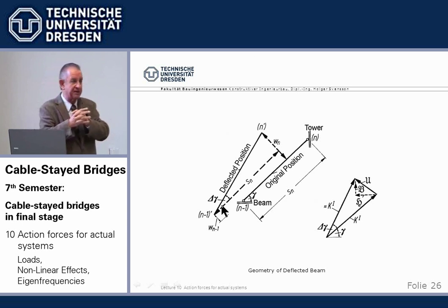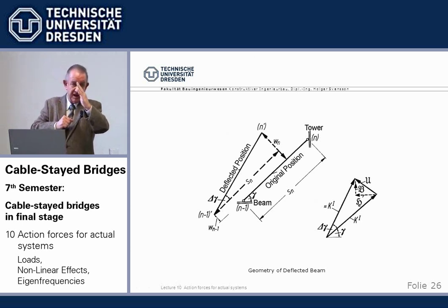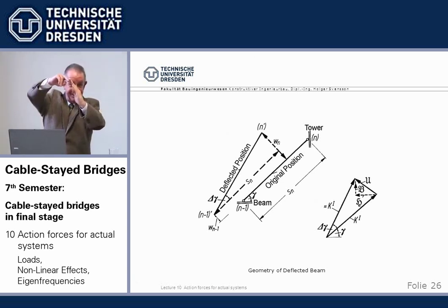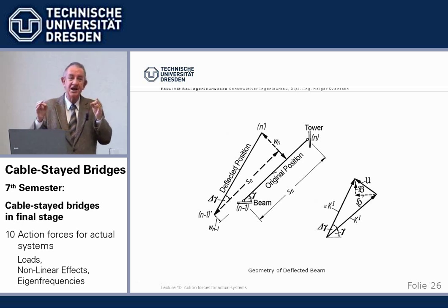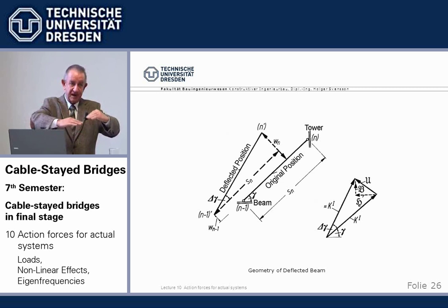So we have the two effects: shifting of the normal force, increase of moment. And we have, at the same time, the cable is steeper. Well, this is fixed, you have to say so. And by that, it unloads the beam. And these two effects work against one another. The shifting of the normal force is governing, but it's not as big as it would be without the steeper cables. That you should remember. Thank God for the second part, otherwise we couldn't do these nice slender bridge beams.